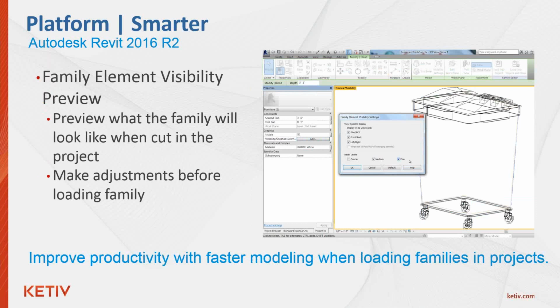All right, so the family element visibility preview feature, excuse me on that, helps you see your design intent by filtering out geometries that are not viewed and making only the geometry that will be loaded into your project visible. You can work more quickly by previewing the geometries and making your adjustments before loading your family into your project. So in plan views, the preview visibility tool setting allows you to preview what your family will look like when loaded into your project environment or when you see it in a projection view. So now with this benefit, you can improve productivity with faster modeling when loading your families into projects, by making it easier to create the family with the precise desired behavior.